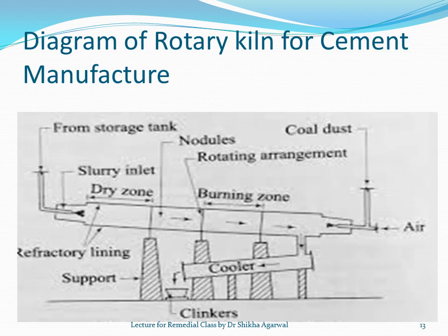Now this is the diagram of the rotary kiln method. You can see that it is a long kiln. The slurry is fed from one end and heating is done from the other end. Therefore, the temperature decreases from bottom to top. So in the drying zone, which is just near where the slurry is added, the temperature is 100 to 500.